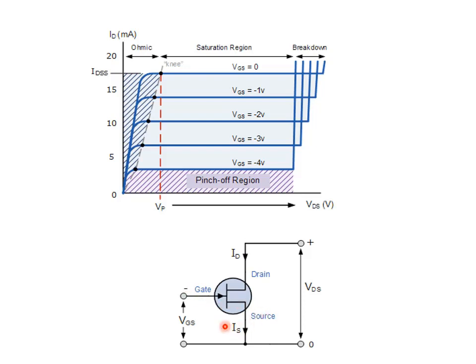So this is usually how we connect the FET transistor. So the voltage here and the current, the drain current, this is the current that we want to control, the drain to source current. And this current is controlled by the gate, and the gate voltage will decide how much current will flow in this direction. So this current is determined by the gate.